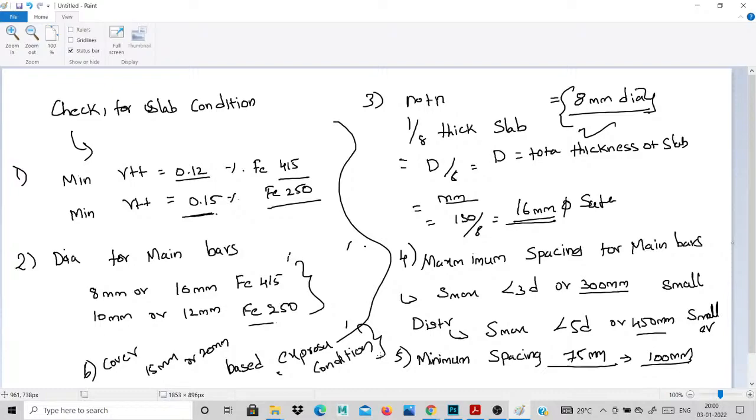For the slab, first you calculate the span by depth ratio, then you go for load from the code books, then bending moment for one way and continuous two ways. You calculate the edge conditions for short edge, short support and simple support, then calculate the Ast. Then you calculate the deflection check, percentage of tension reinforcement and depth of the slab. These two checks are the main ones.